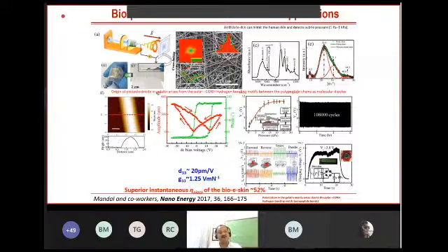Then the question comes, how can you scale it up? Scale it up means how can you make different thicknesses as per your requirements, and also size and shape, because the swim bladder and this fish scale have a limitation, right? So we adopted a technique where we use the gelatin made from fish scale, and again we adopt the electrospinning technique. You see this particular image, and you see the gelatin-based nanofiber we have produced, and this is the microscopic way to prove it.